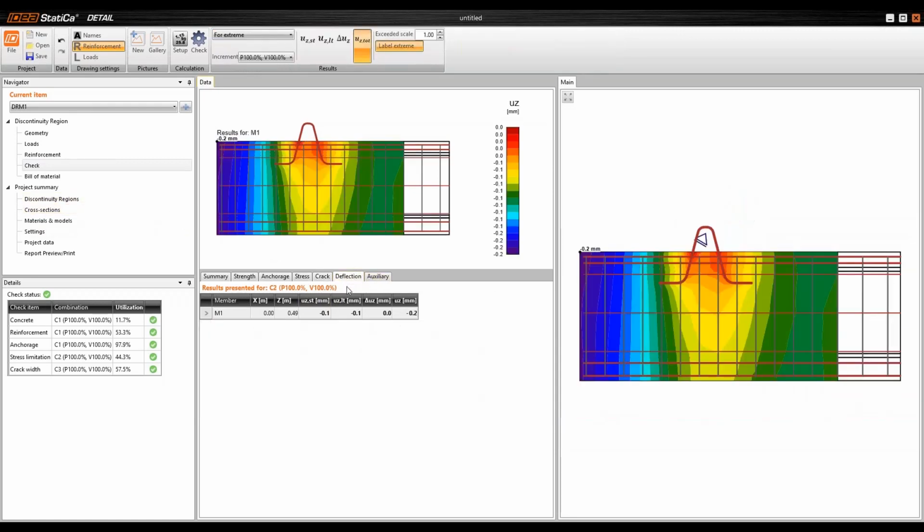And the last thing is the deflection. Here, as I mentioned, sometimes it's a little bit tricky to display because it's a trimmed end of the beam, and it means we are not sure of the boundary conditions at the other part of the beam, so we do not really display the deflection, but we can see only the values here.